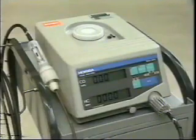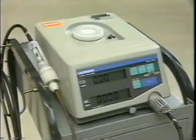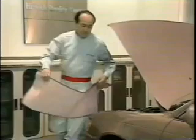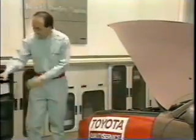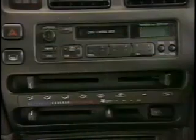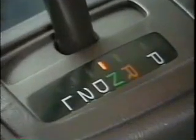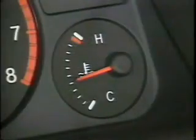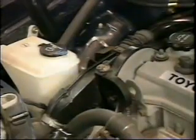Now, let's see how to adjust the idle speed and mixture. You should use a CO meter to do this if possible. First, in order to adjust the speed mixture properly, we must make sure that the following conditions are met. Make sure that all the electrical accessories are turned off. Check to see that the transmission is in neutral. Make sure that the engine is warmed up. Confirm that the ignition timing is set properly.